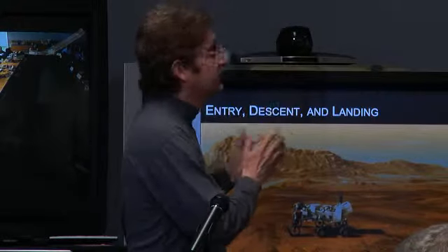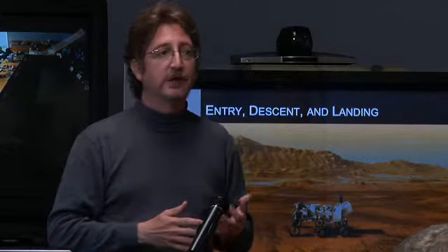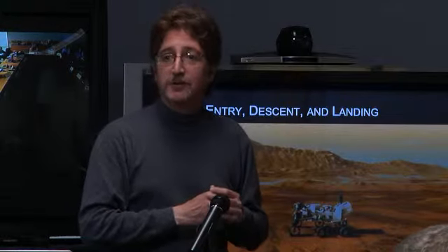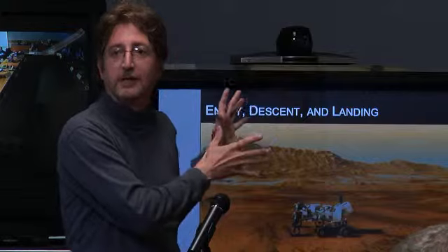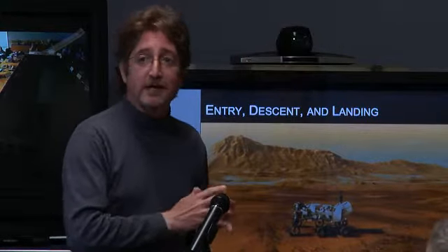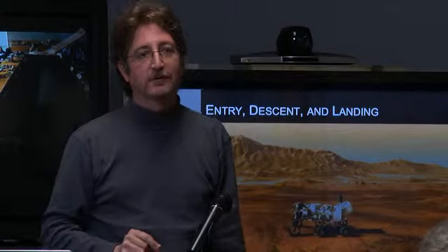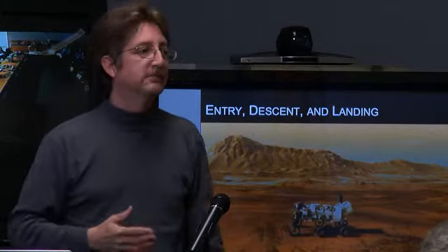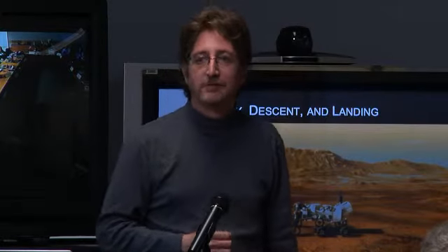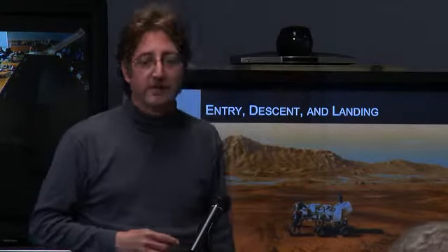Okay. So this leads to the subject of the presentation, modeling and simulation. There is an end-to-end simulation of this whole process. This is an animation. This was created by graphic artists to look good. Okay, but there is, and they do a very good job, and we use these animations all the time, but it's just that, an animation. We have an end-to-end simulation that basically takes everything into account from the time the spacecraft touches the atmosphere to the time it comes to rest at the surface. Okay, and because we have a large computer bank, we can run about 10 to 20,000 simulations overnight, and we run that pretty much every night.